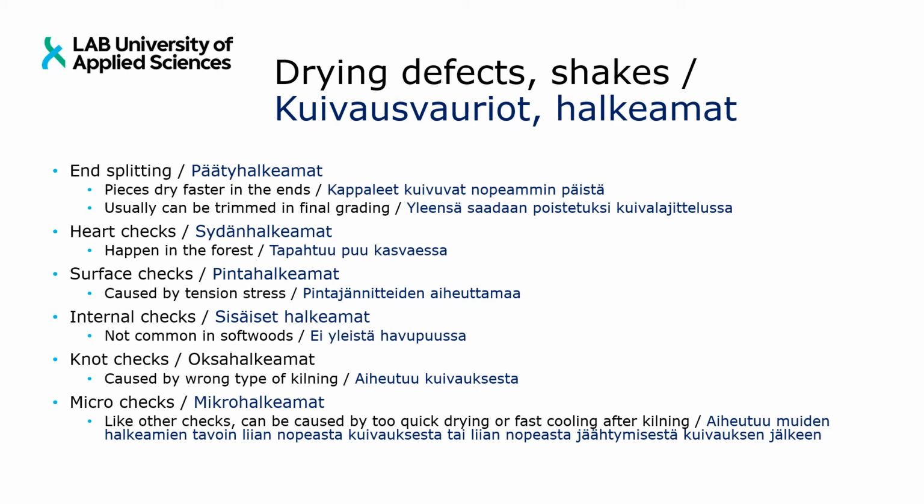Then there are, of course, also these micro checks like we have been talking about before, and they might be caused by too quick drying or too fast cooling. In the wintertime, once the goods are coming out of the kilns, the temperature is still a lot higher than the outside temperature. If you let it cool very quickly, that again might cause some shakes to the surface.